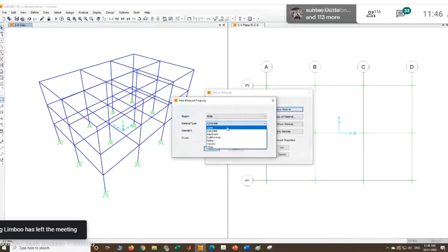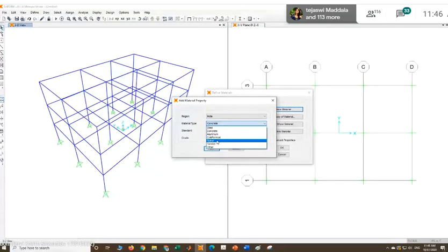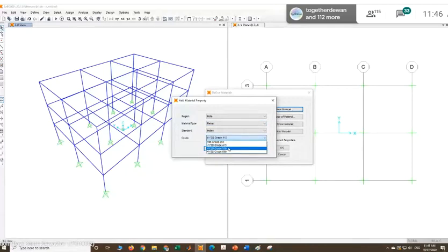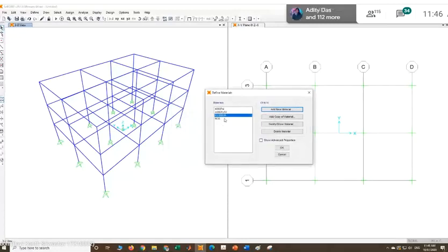You can see here the steel is there. This is for assigning steel sections like ISMB, something like that. But if it is an RCC building, a reinforced concrete building, we can go to rebar. Rebar is nothing but, technically, reinforcement. It can also ask what reinforcement you want. It's mild steel or HYSD bars. These days only HYSD 415 and 500 are used. So I'm using HYSD 500 for this purpose. So HYSD 500 rebar I've created. So I've defined these two materials. Okay.